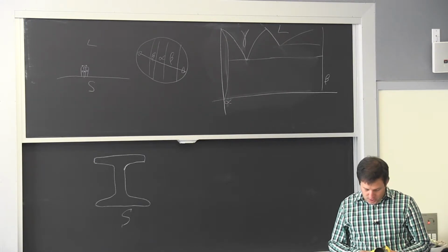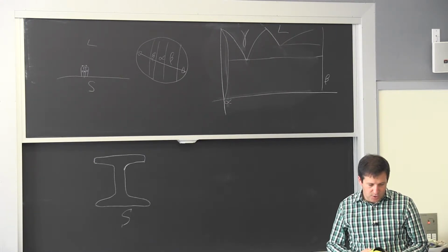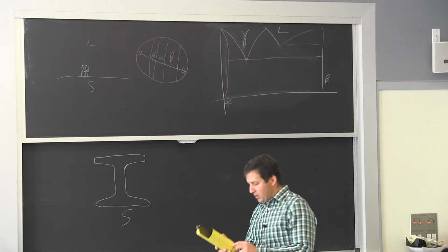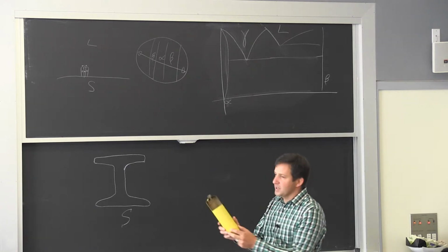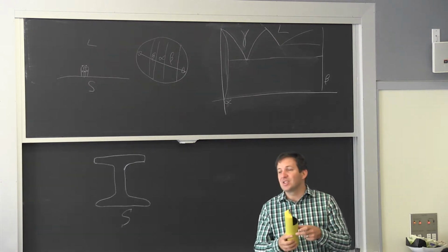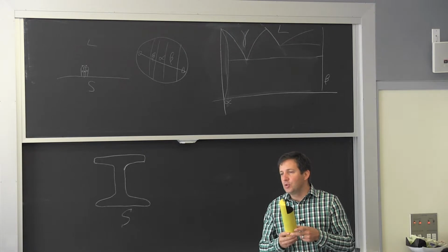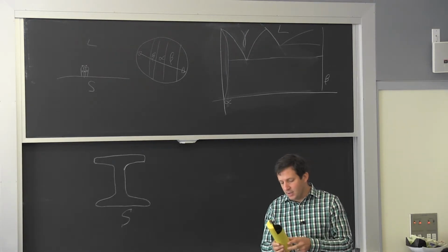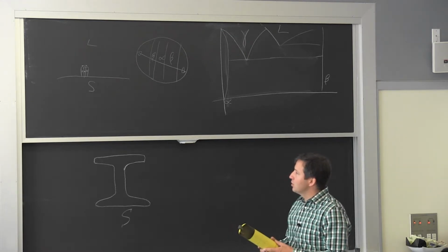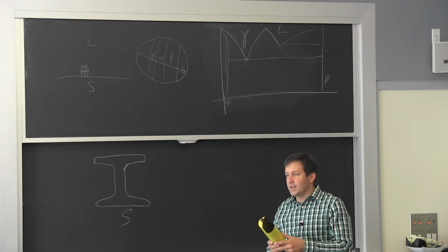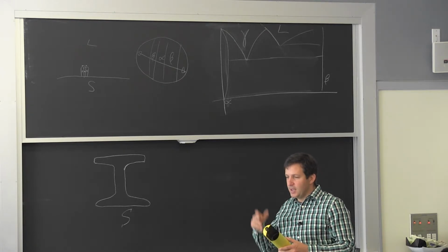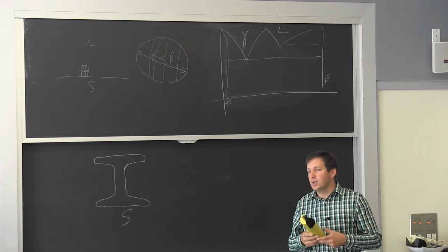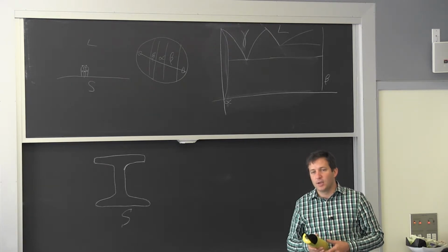Deep drawing. The aluminum can is a good example. What is very particular to deep drawing is all that material, so when you go around the corner, it's bent, but then it has tremendous tension. So you do need your material to have a lot of hardening. So if you're going to do it on steel or brass, it's very typical to stop in the process, cool it off, heat it up to soften it, and then you continue. Because you want to continue having enough hardening.